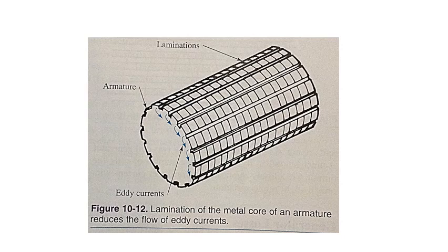Hysteresis. The third loss occurring in a generator is called hysteresis loss. Hysteresis is also called molecular friction. As the armature rotates in the fixed magnetic field, many of the magnetic particles in the armature core remain lined up with the fixed field. These particles then rotate against those not lined up in the field. This rotation causes internal friction between the magnetic particles and creates a heat loss.